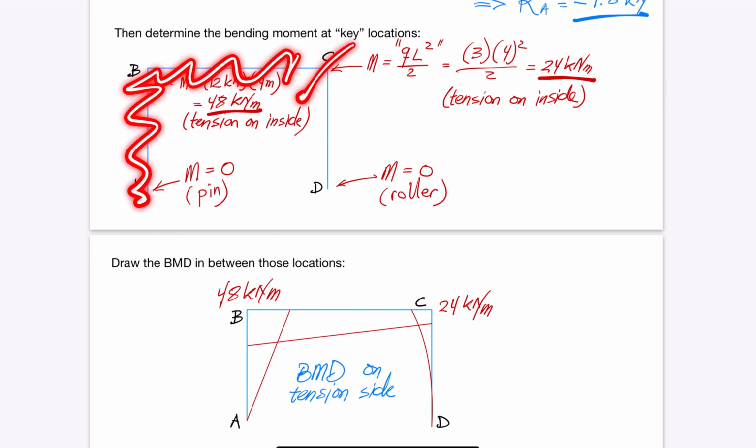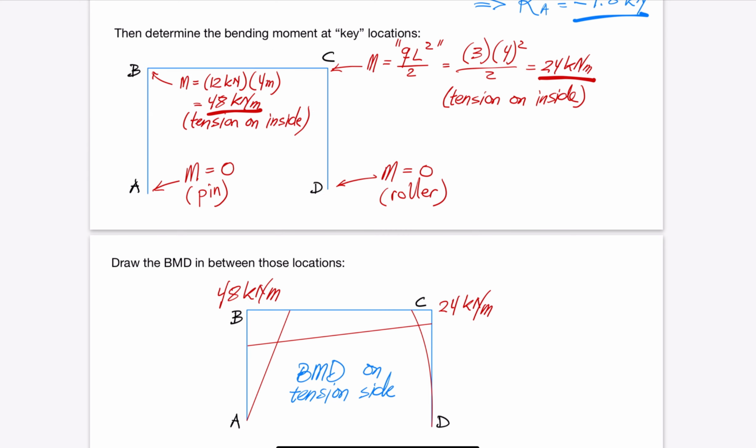We arbitrarily select to hold the column from C to D in this manner. Holding the other end, the L-shaped portion from A to B to C, would give exactly the same bending moment. Notice here that the portion we are holding is a cantilevered column with uniformly distributed load. We have analyzed such a structure in an earlier video, so we now simply state that the moment value is QL squared over 2. The value is 24 kNm.